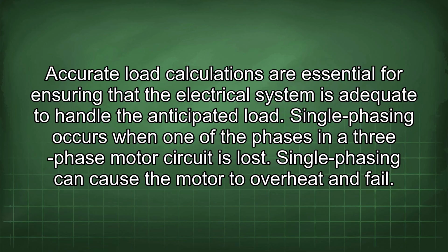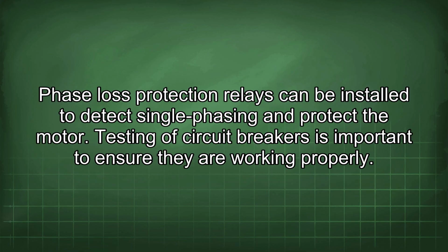Single phasing occurs when one of the phases in a three-phase motor circuit is lost. Single phasing can cause the motor to overheat and fail. Phase loss protection relays can be installed to detect single phasing and protect the motor. Testing of circuit breakers is important to ensure they are working properly.